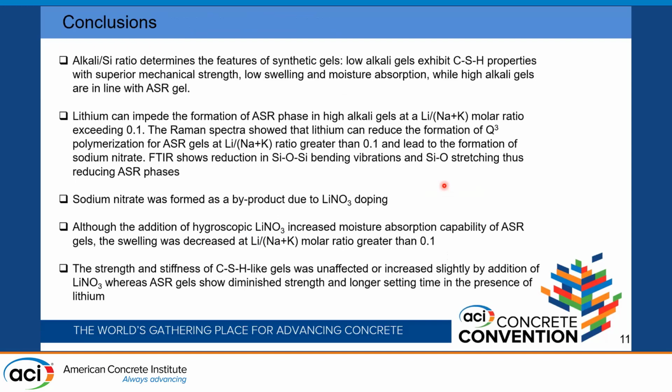Now, to go to the conclusions, we will just summarize the points. So the behavior of the synthetic gels depends on the alkali to silica ratio, and the low alkali gels display CSH-like properties having low swelling and high mechanical strength and stiffness, while the high alkali or ASR-like gels show high swelling and moisture absorption, as well as lower mechanical strength.